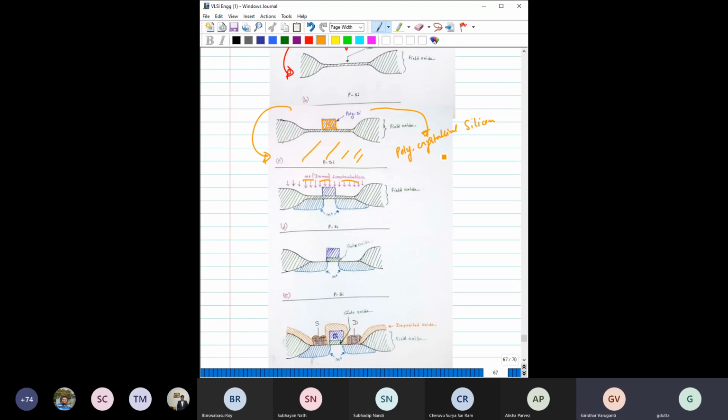That is the thing. Polycrystalline means its orientation is, say if I say like this orientation is 100, then the orientation of the crystal is fixed here. But for this polycrystalline, actually there might be many orientations inside these regions. It may be 100 in some region, some 110 region, maybe 111, like that. So that is what a polysilicon is.